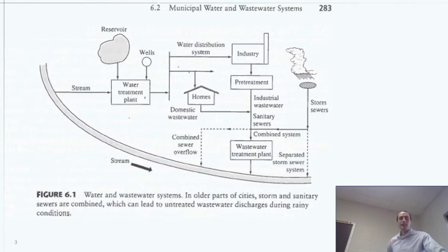So fitting timing here, because one of the things that has happened in the past is people have at first thought of the issue that I just described, right? This junk that's going straight into our waterway. They thought, well, why not just send that to the wastewater treatment plant, right? It's kind of nasty. Well, there's a problem with that. If we combine the storm and sanitary sewers there, then if we have a lot of storm, we overflow the wastewater, which is arguably a worse problem than a little bit of extra contamination going into the stream that no one even knows is there.